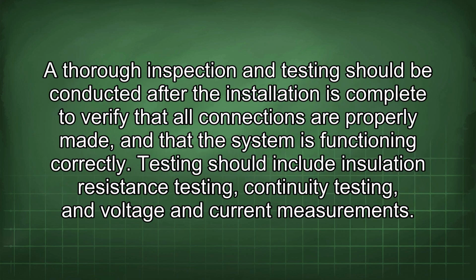A thorough inspection and testing should be conducted after the installation is complete to verify that all connections are properly made and that the system is functioning correctly. Testing should include insulation resistance testing, continuity testing, and voltage and current measurements.